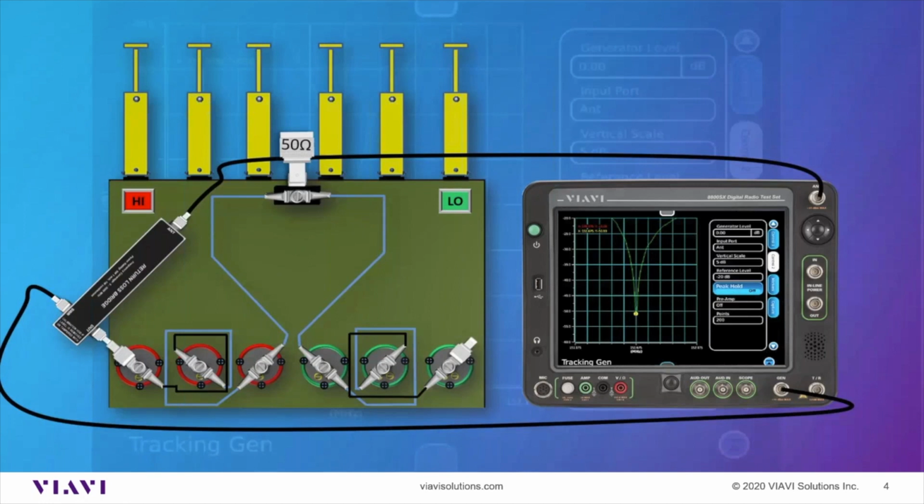Oh, you know, the other thing I probably forgot to mention, and of course you can see it in the video, is that when you do this, you've actually got the 50 ohm load connected to the antenna port, and you have the opposite side of the duplexer, the low pass or the high pass, open at that point. I didn't mention that, but you can see where that load is sitting. So that's a 45-minute process to go through to realign a duplexer.